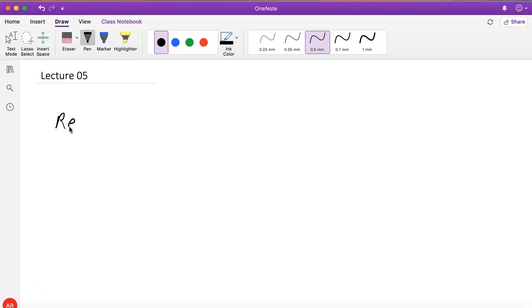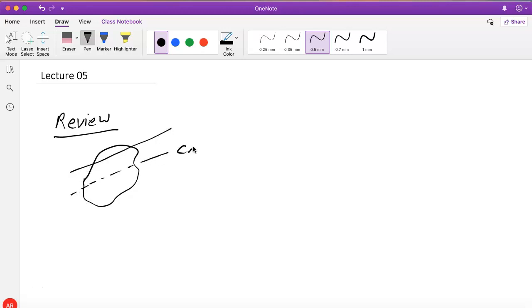Last time we talked about the parallel axis theorem, which allowed us to relate the moments of inertia around different parallel axes, one being in some arbitrary place and the other going through the center of mass. So, the expression we found was, let's say, for some object that can rotate around some axis here, and there's another axis going through the center of mass, which is, let's say, here.